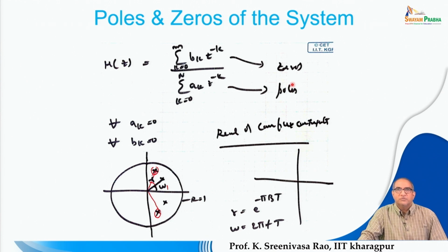And these poles are an indication of the resonances in the system. In the context of speech, a pair of complex conjugate poles provides the resonances, known as the formants of the system. Whereas the zeros, if placed as complex conjugates, provide the anti-resonances of the system.